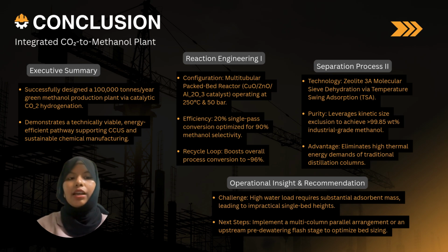For separation, we replace energy intensive distillation with a zeolite 3A molecular sieve system using temperature swing adsorption, leveraging kinetic size exclusion, where 3 angstrom pores adsorb the 2.65 angstrom water molecule while excluding methanol. This purifies the product up to 99.85% industrial grade purity. So the operational recommendation to overcome the practical single bed height constraint from high water loading,